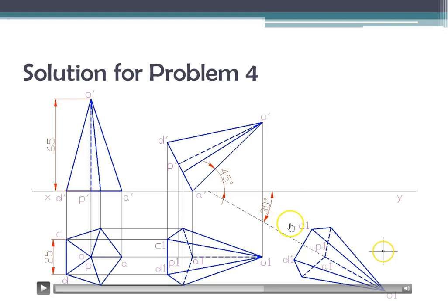You have to actually represent the true axis length being inclined at 30 degrees, and based on the true length you have to position your view, because whatever view of axis you are getting in this top view is actually the foreshortened length of the true length of the axis. So if the question says the top view of the axis is inclined, this construction technique is fine.